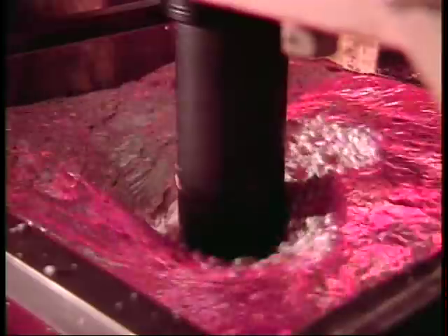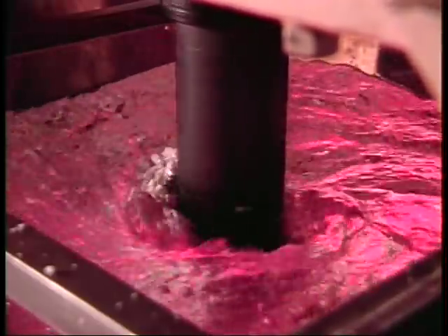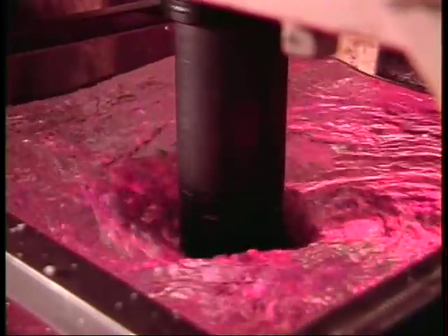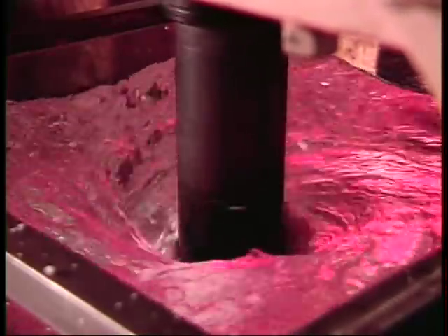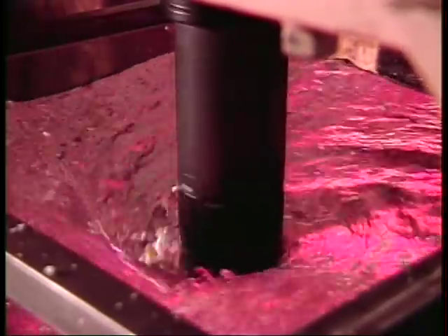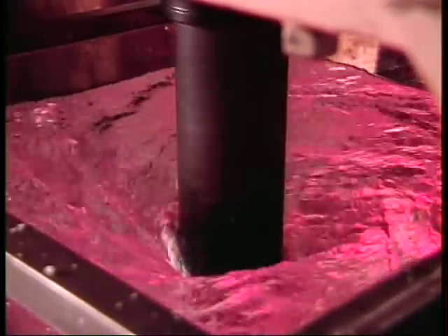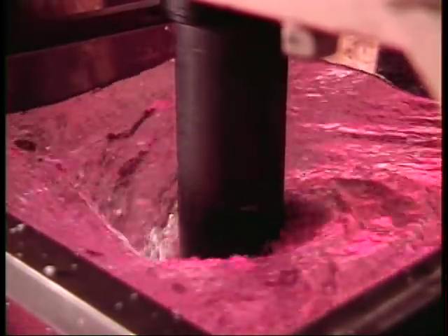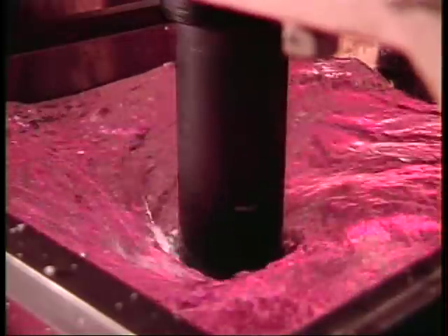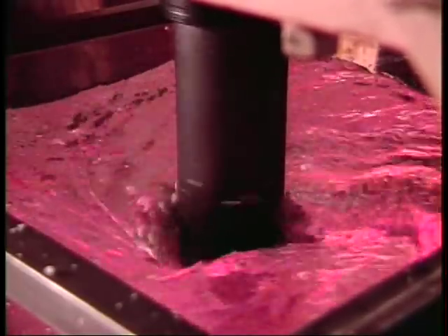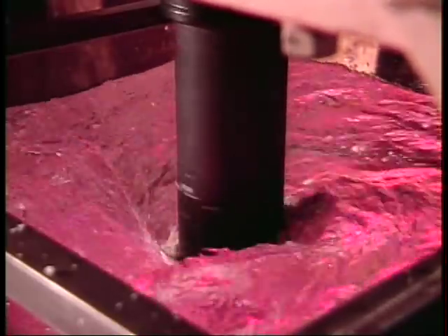In this next sequence, a much higher rotational velocity was used to demonstrate the effect of vortex formation on the surface. Particles were once again added that form a supernate because of their low density. In the case of unidirectional rotation, clearly a free surface vortex can be seen, and ingestion of the particles under the metal surface, or in this case, liquid surface, is evident.